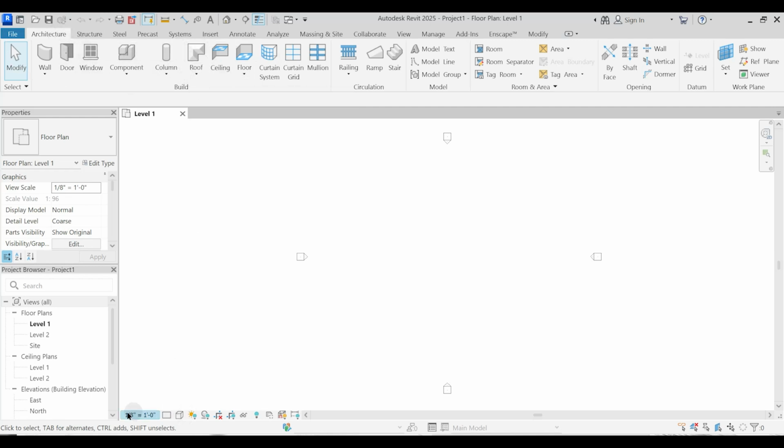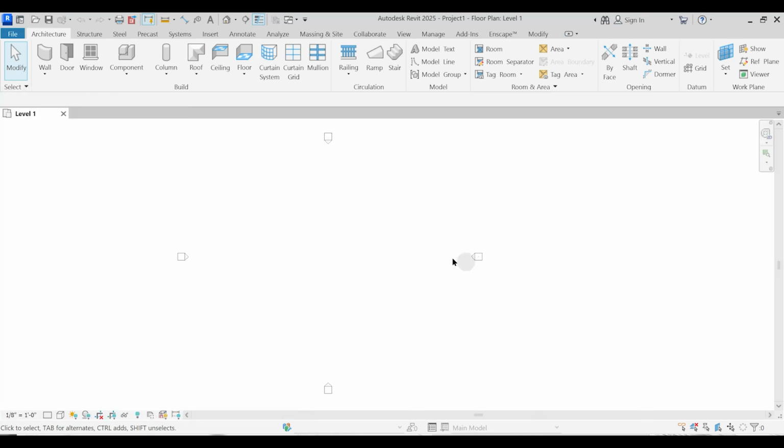Okay. And last is the bottom taskbar, visibility settings. This is called bottom taskbar visibility settings. Okay. This is called the toolbar. This is the properties toolbar and this is the project browser toolbar. Many of you might end up opening a blank screen of Revit. Might happen in your case, which has only these elevation markers and this level 1, but you don't have anything, no toolbar loaded. Just like AutoCAD, we have toolbars here in Revit also.